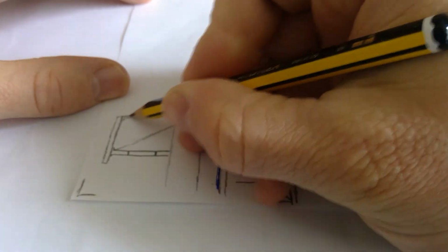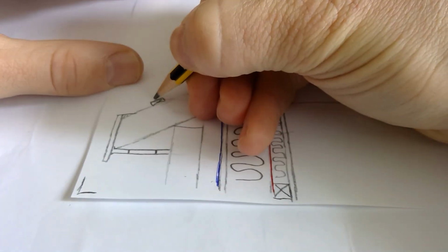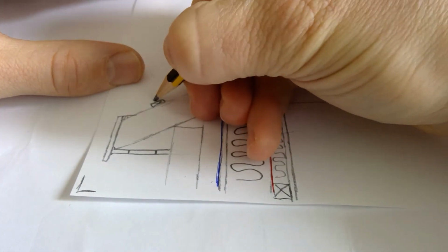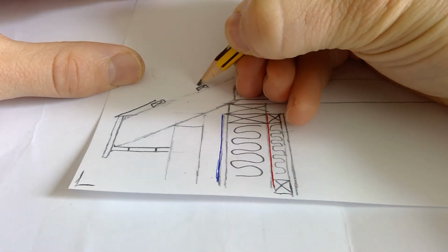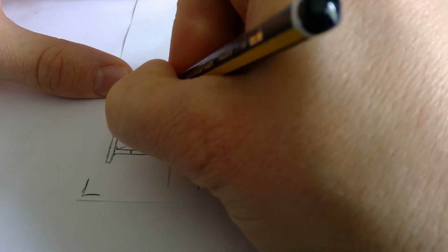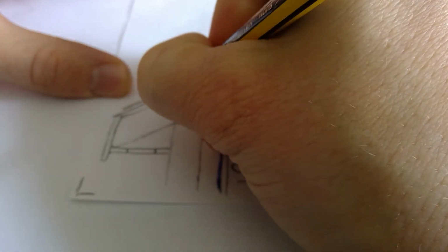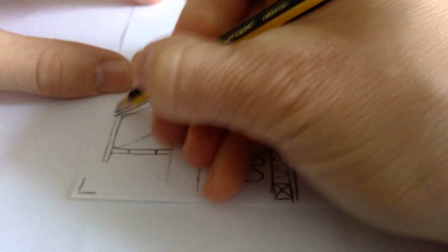So how far is this one? Just half. This batten is halfway between here and here. So a quarter of a slate they cut first, and that rests down over. Half a slate here. Again, try and make it, now this is a bit untidy, try and make it so we have straight first of all, and you have a slight gap. That's not a great effort there, but to have a slight gap in between those. Make sure that comes down past over there, by the way.